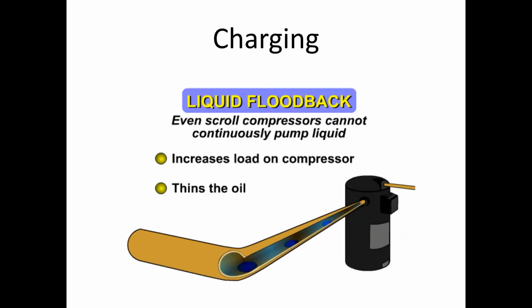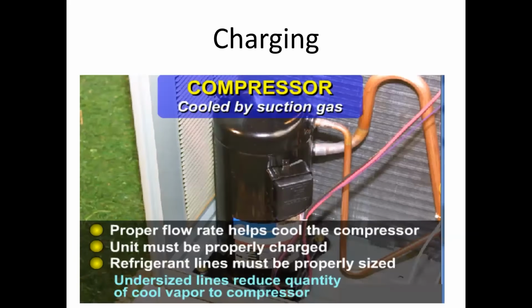Whether by design or by accident, our compressor is not a liquid pump, it's a vapor pump. So if you have experienced that failure mode, it's because that compressor is being asked to compress liquid and you can't compress it.